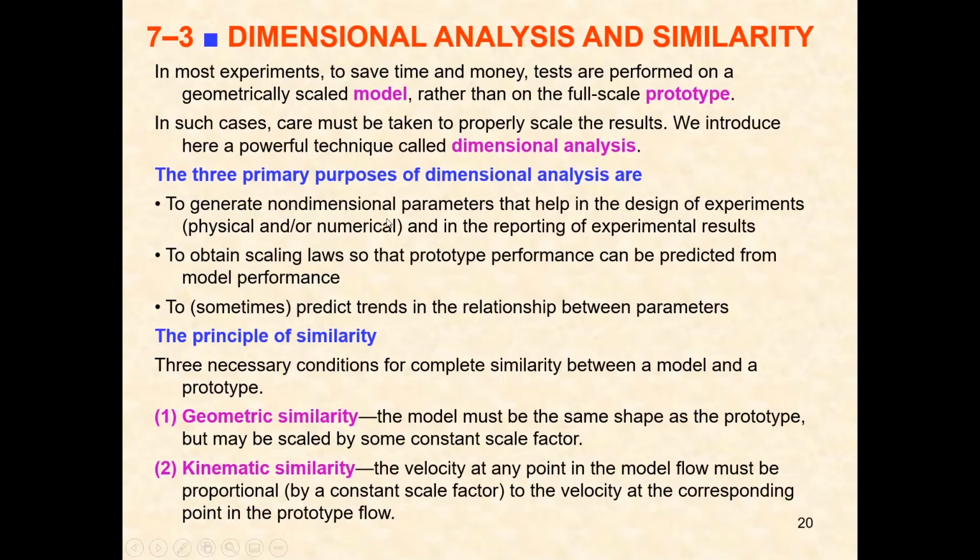The three primary purposes of dimensional analysis are to generate non-dimensional parameters that help in the design of experiments, either physical or numerical, whether you want to do experiments or simulations, and in the reporting of experimental results; to obtain scaling laws so that the prototype performance can be predicted from model performance; and to predict trends in the relationship between parameters. The principle of similarity begins with geometric similarity, where the model must be the same shape as the prototype, but scaled down by some constant scale factor.